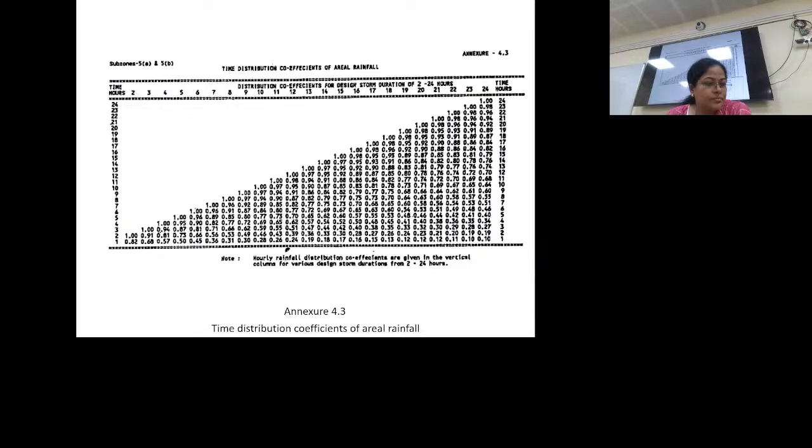Initially, what we assume from this analysis is that the hydrograph is very steep, so the initial rainfall is very high, and as the storm duration goes on, the rainfall reduces. Based on this conversion, you get the hourly distribution of the rainfall. That hourly distribution you now have, and you know the unit hydrograph. You multiply those rainfall coordinates into the unit hydrograph for that duration.